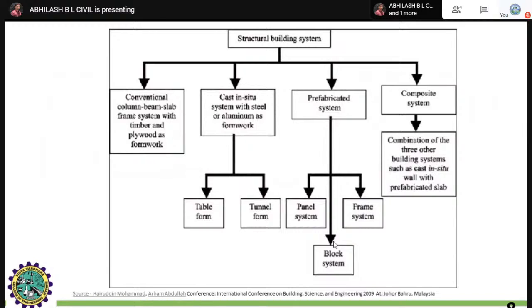If you go to the conventional method of construction, you can observe the first thing is you will procure the site. Next, marking of the particular site with respect to execution planning. Later on, you will excavate the earth for the foundation purpose, right? After excavating that particular earth, what next? Whether you will lay the concreting part for the foundation directly, no, right? You will go step by step. The first thing is PCC, that is plain cement concrete bed, you will lay for the particular foundation.